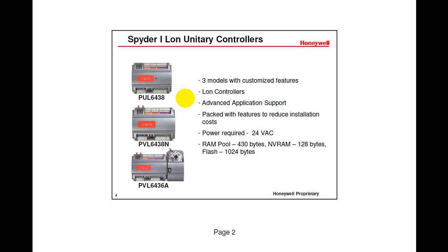Here TR75 comes with schedules, where you can configure the Spyder schedule directly from TR75. TR71 gives you the option to configure the set points and PID parameters. You can change those values directly from the module. Then TR42 will allow you to override your set points. TR40 doesn't come with a display, but TR42 comes with a display. So that's how these parts, going to the higher versions, have some additional features.